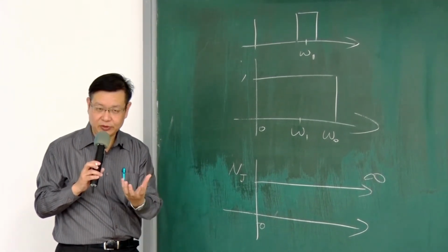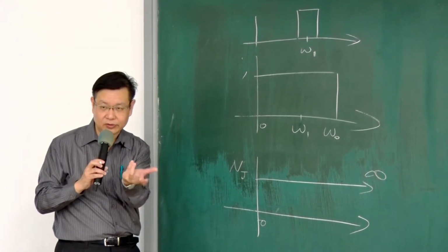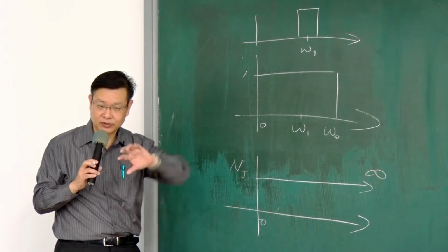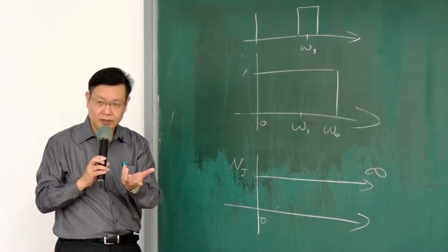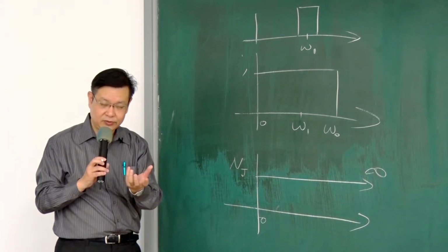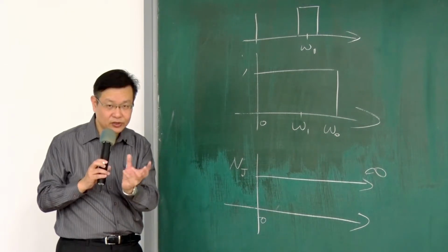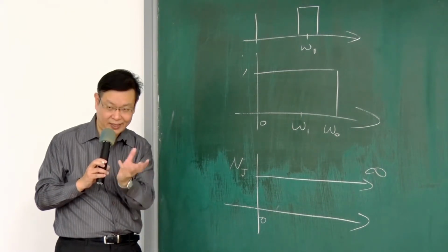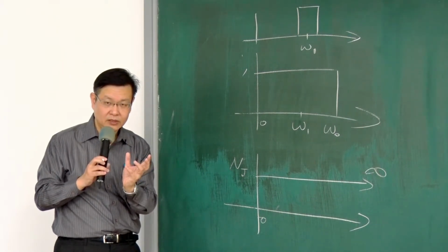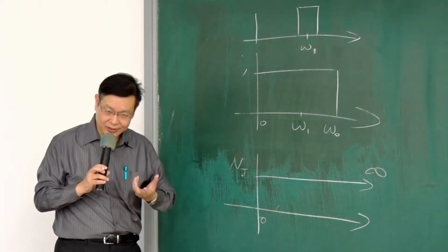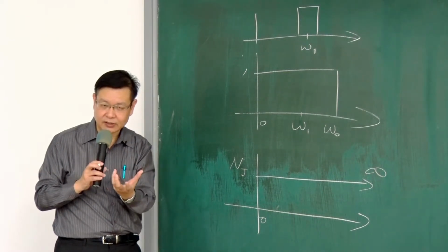So the movement of the object can be divided into linear translation and rotation in 3-dimensional direction. The accelerometer is used to measure the linear acceleration, but the gyroscope is used to measure the rotation, how fast you rotate. If you have information about the translation and the rotation of the object, you totally understand